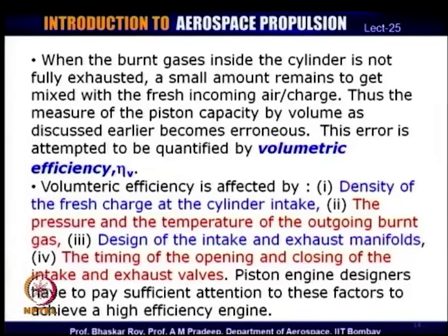So, all the burned gases do not go out of the cylinder, a very small amount remains, and when the intake valve opens and the fresh charge or fresh air comes in, it gets mixed with the fresh air, and as a result what you get finally is a combination of fresh air charge and a certain amount of residual burned gases that has remained after the exhaust stroke.